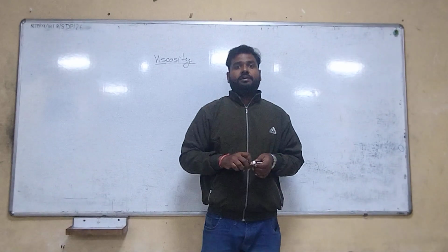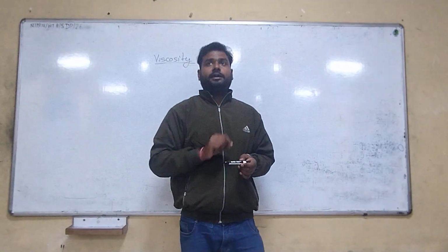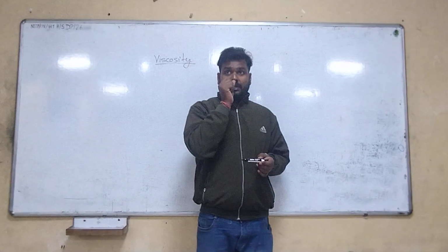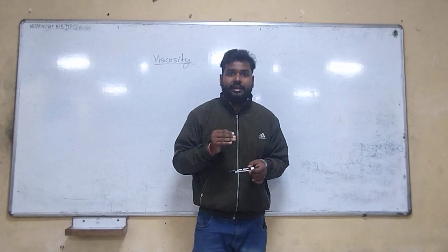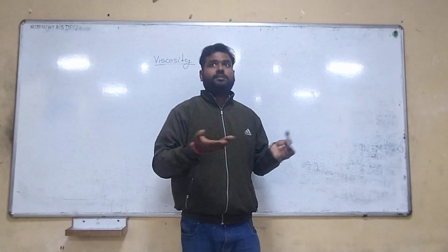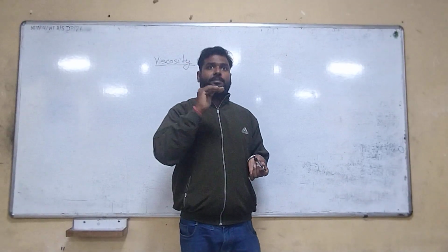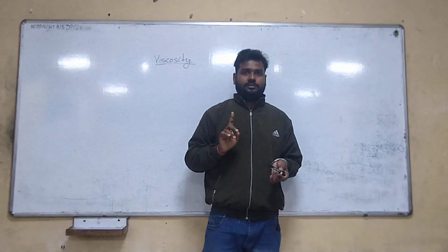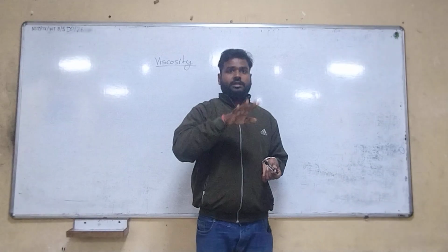But when we come to real fluid, it follows a condition, that is the no slip boundary condition. No slip boundary condition means the layer which is just in contact with the boundary, or any other particles or surface, remains in the same motion. If the boundary is at rest, the layer in contact with that boundary is also at rest, and the layer is in motion if the boundary is in motion.